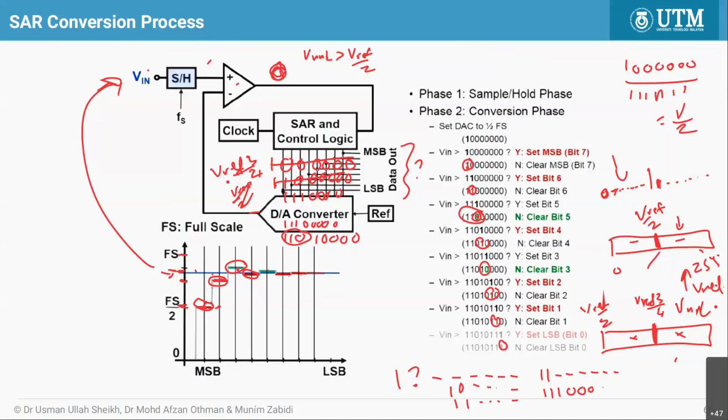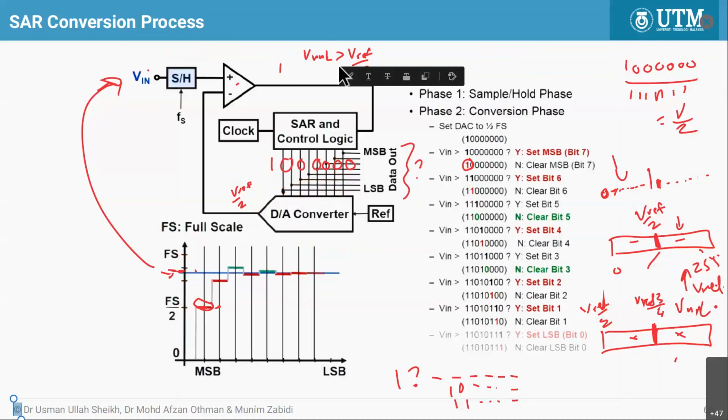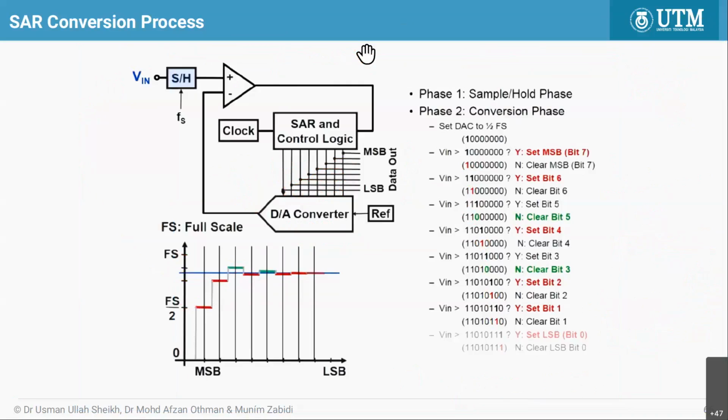What is the color indicating, sir? The color indicates whether the test voltage is less or greater than the unknown value. If it is red, it means the unknown voltage is greater than the test voltage. So this is like a test voltage: it will test, and it's like you're trying to guess. I give you a number.